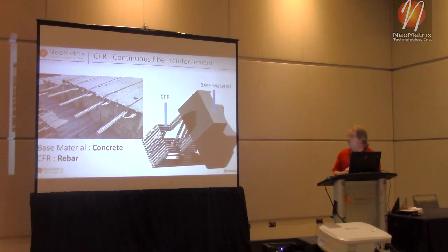The other thing that Markforged printers do that a lot of other printers don't is the ability to add continuous fiber reinforcement. So you get your base material, the Onyx, and then you can add continuous carbon fibers. So this is, again, using the concrete analogy. If we've got our concrete and then adding rebar adds that additional strength, that's exactly what we're doing with the continuous fiber reinforcement in the base Onyx part.